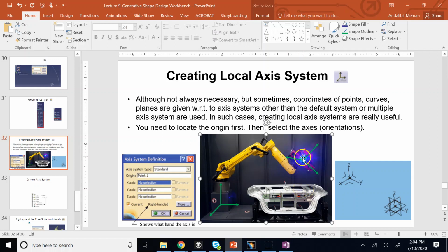Of course, with respect to the coordinate frame that is attached to the device, because they are measured by the device, right? Not directly by the original fixed coordinate frame of the robot, which we call the base coordinate frame. We call this the end effector coordinate frame. So here you see I'm specifying these points with respect to a secondary coordinate frame. That's the same thing in CATIA.